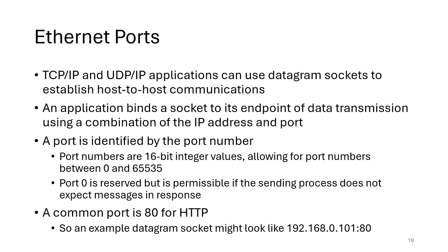You won't always see port numbers. Often the port number is assumed, and with many industrial protocols, they default to a port that can't be changed. So for example, Modbus defaults to port 502 and you can't change it. So again, from a firewall point of view, if you blocked port 502, that would block any Modbus TCP communications over that network.